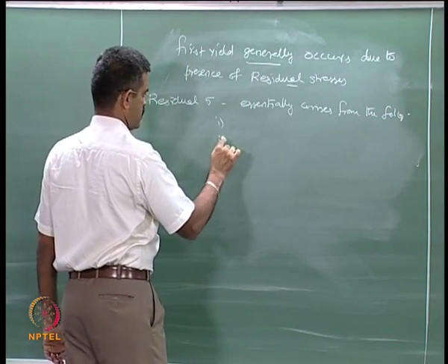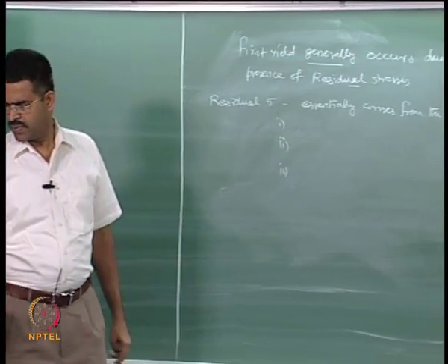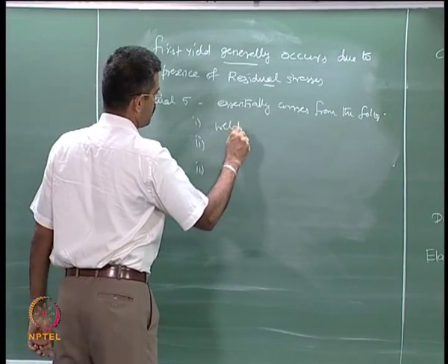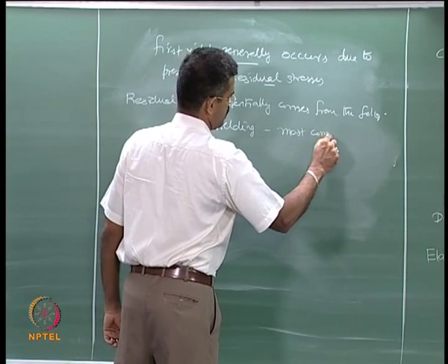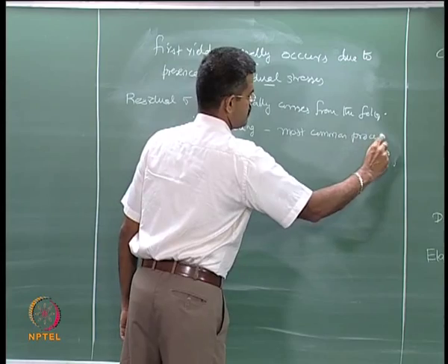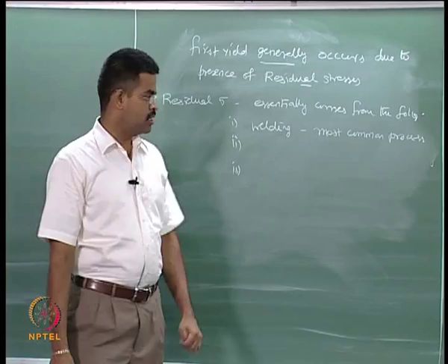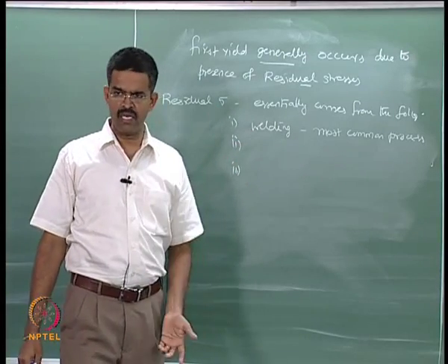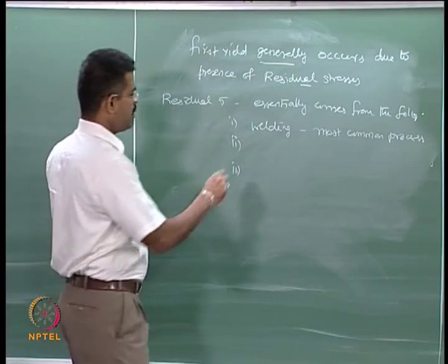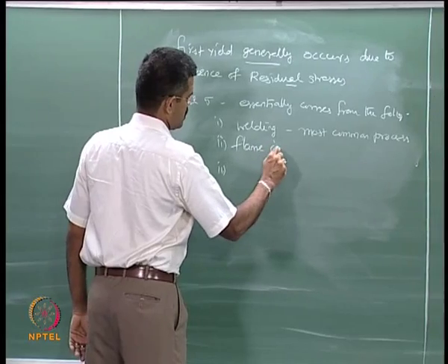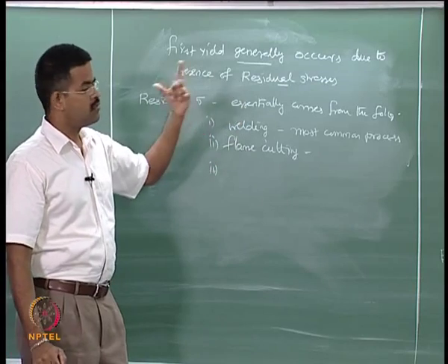One, because of the welding process, which is the most common process in marine structures. I mean, you cannot construct a marine structure without welding. The moment you do welding, it will initiate or start accelerating formation of residual stresses. The second process which is very common in marine structures is flame cutting, which is also responsible for formation of residual stresses.